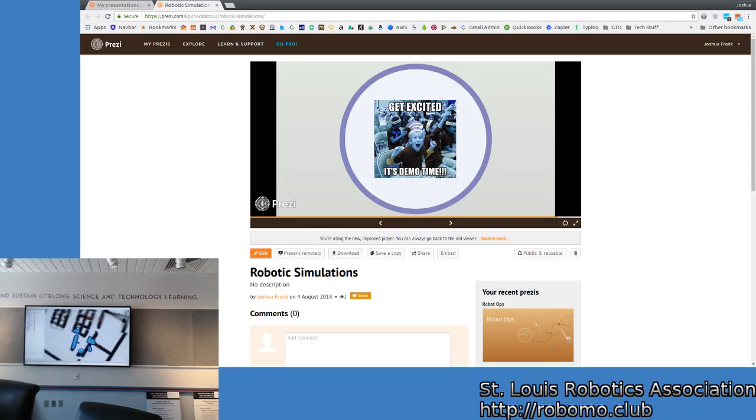Okay, so the first thing you need to do for a robot that's not using SLAM, simultaneous localization and mapping, since it's in a static map, is tell it where it is, or give it an approximation of where it is. In this one, you just kind of visually have to look, and I can tell there are two doors there. It's kind of in that door. There's the cubicle. I think if I flip this around like this, this is the view that we're getting.